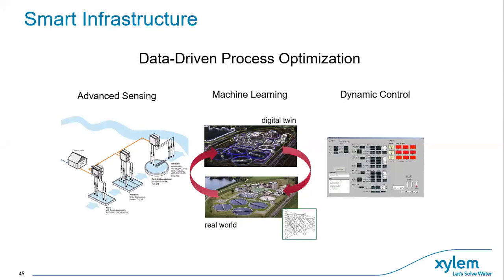That's not just taking the aeration part of the works, but looking at the full treatment works and how that can drive efficiency. So taking the primary settlement tanks, optimizing them, understanding how that can impact what happens in the secondary biological treatment step, and really using all the different elements of the works to get much better control, much better performance.